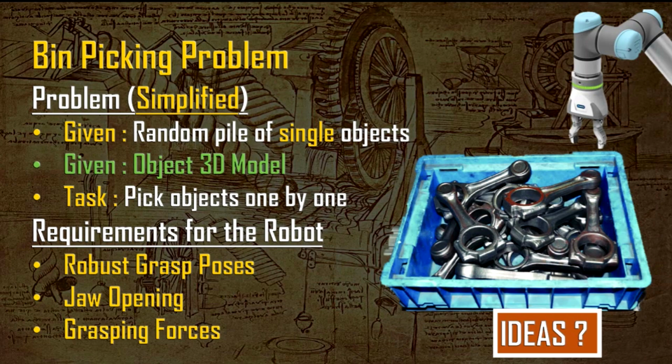Are you aware of the inverse and forward kinematics models, maybe? Yes. So once you determine the grasp poses from a deep learning system or any other way, you feed it to the end effector position, and with inverse kinematics we get the joint positions. All the joints go to that position, and it goes to the grasping position. Then maybe you give the command of closing the jaw and picking up and going to a home position. Was that your question?